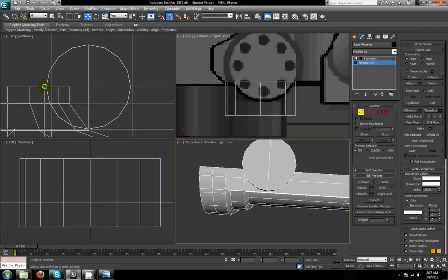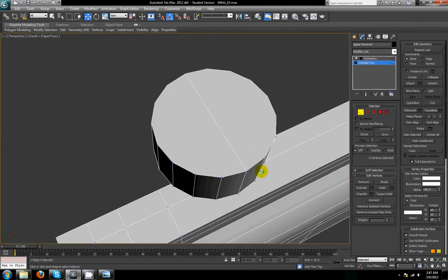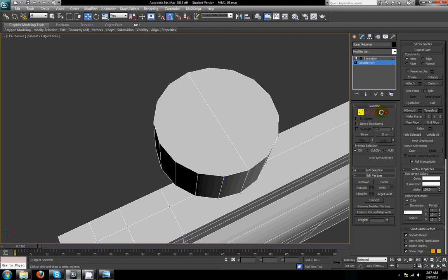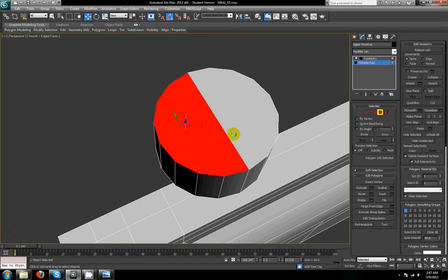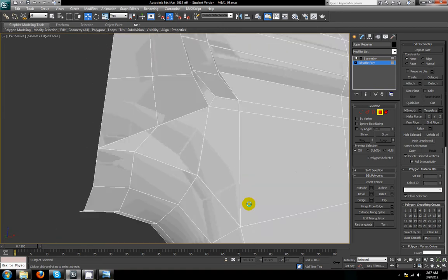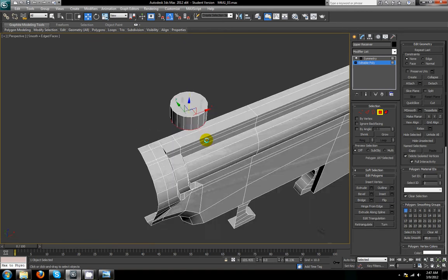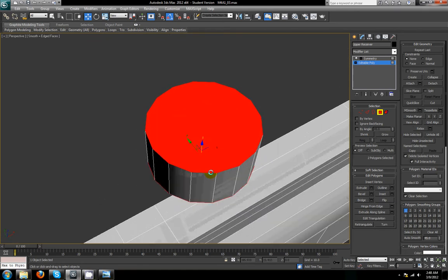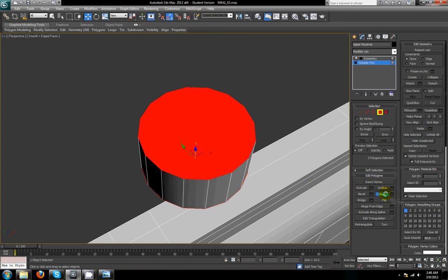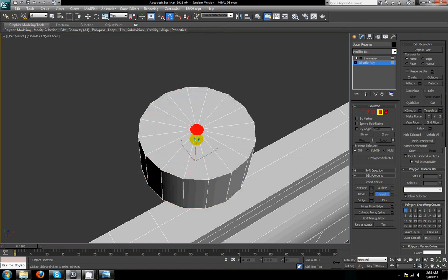And I think I'm going to do the same thing with the middle points as well. Except now that we have this line here in the center, actually, you know what? There's a much easier way to do that. I think I'm just going to select the faces on the inside, and I'm going to do this little function here called Inset. What Inset does, if you just select the regular Inset function instead of the settings mode, if you hold the left mouse button in, you can just kind of create exactly what you think it is.